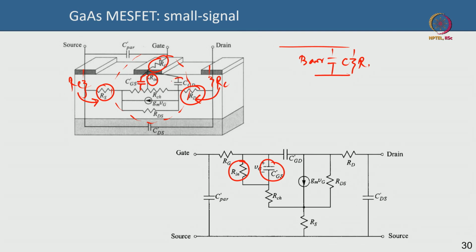Then there is this gate drain capacitance, very important. It is the coupling between the gate metal and the drain side of the channel, okay. At that point, once you have the source and the drain excess resistance, at that point where it terminates, your drain will couple to the gate, and that is your gate drain capacitance. RCH is the channel resistance, the 2DEG has its own resistance, so that is your R channel, and that is in series with the CGS, of course.